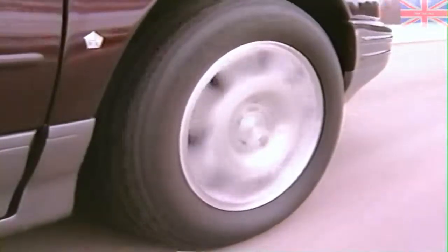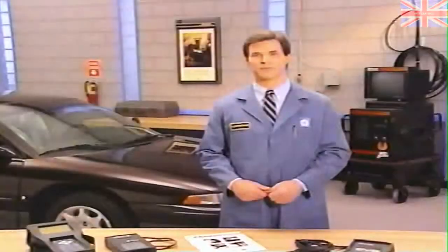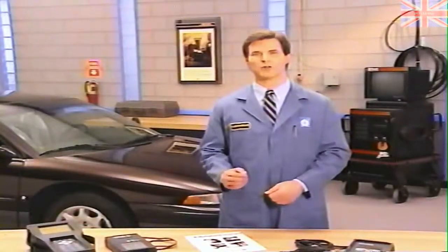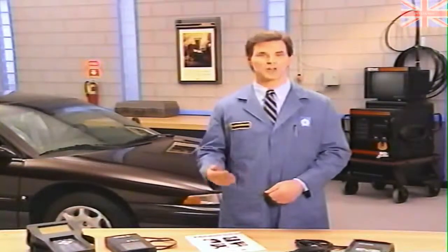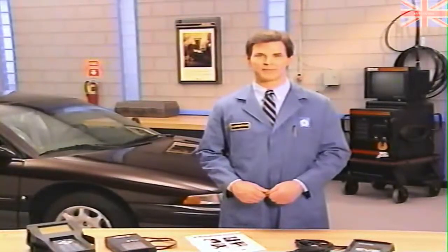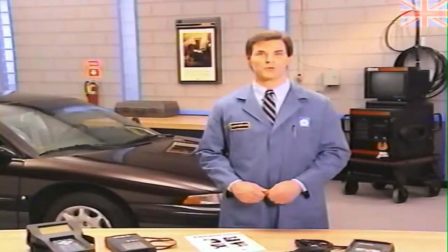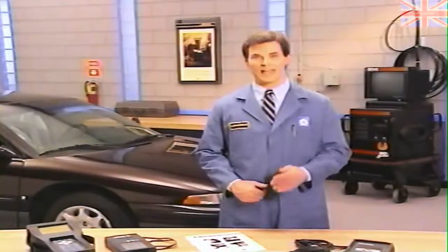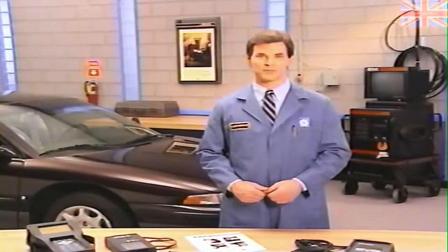Each rotates at a different speed due to transaxle and differential gear ratios. You can pinpoint the component group responsible for a measured vibration by determining the rotational speed of each group. Problem vibrations that match the first, second, or third order frequencies of the major component groups indicate that the cause is most likely located within these groups.